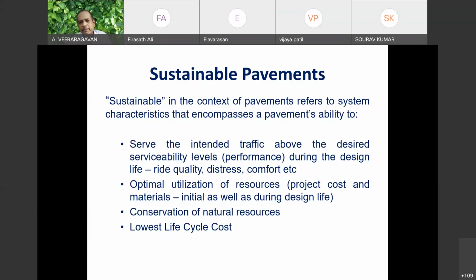So this can be called roughness. It can be called the International Roughness Index, and how much the value will change. A very good road can have a roughness of less than 1500 millimeters per kilometer. If the roughness is around 1500 millimeters per kilometer, then you feel comfortable. You can sip a cup of tea in your car. Less than 1500, you can easily do that without the tea spilling on your shirt. I call it a smooth surface. Glass roughness is 0. You can imagine that, 0.